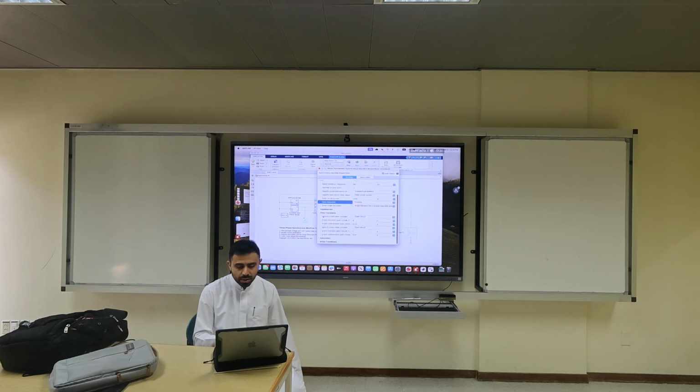There is another thing, the time constant, QD axis. We'll talk a little bit about it. And then there is a saturation. Here we don't have a saturation. There are initial conditions. Usually initial conditions are rated conditions, or half. Here active power is 250, reactive power is 15. Usually it's around rated. Clear? Don't change anything. Again, you can open the documentation here.